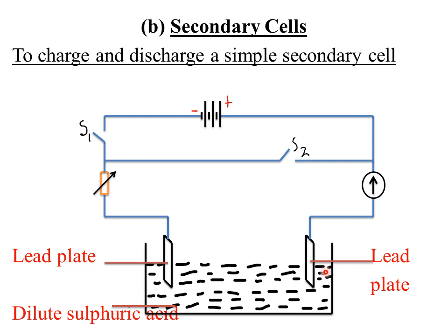So the oxygen reacts with the lead plate that is on the positive terminal to form lead 4 oxide, which is deposited at the anode. So that deposition, that is what we were calling, it turns into dark brown. So the anode turns into dark brown. So that dark brown color is the lead 4 oxide that has actually formed as a result of reaction between